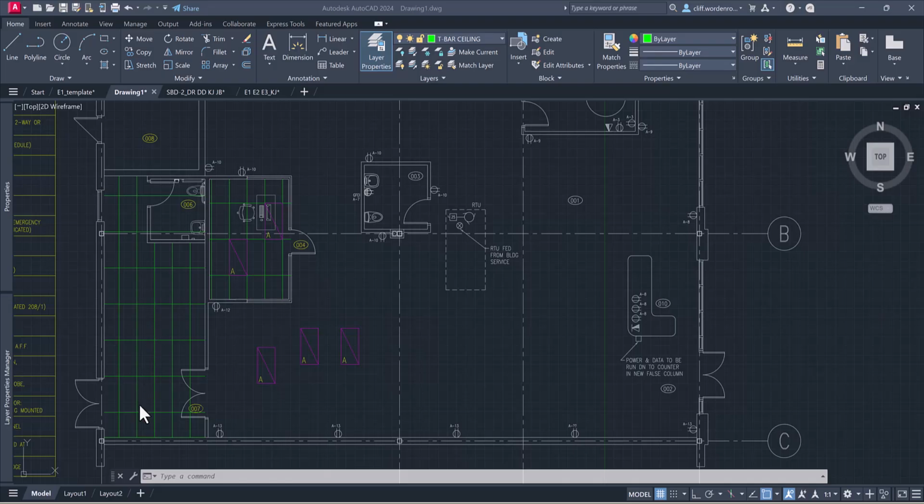So the way I like to do it is I like to kind of count out ceiling tiles and then space them out accordingly. So we do have a space in here, all right? So I'm going to count the big tiles. So I'm going to leave this one alone. I'm just going to go 1, 2, 3, 4, 5, 6, right? So 6, 3 lamps between. So if I go, say, 1, 2, 3, that'll give me 2 spaces between, right?